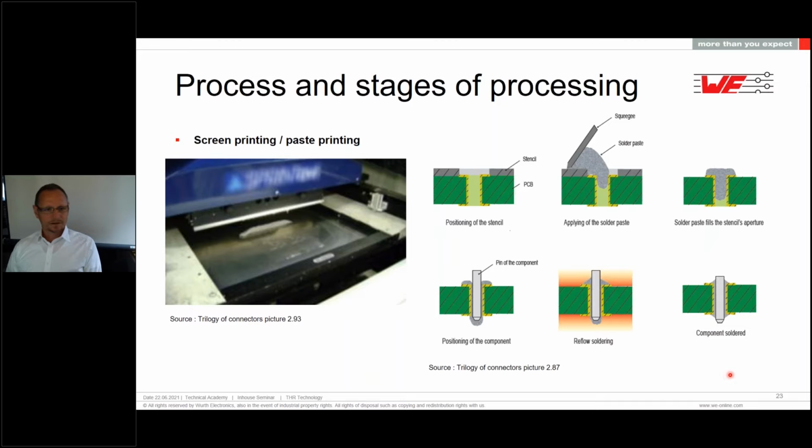Yeah. If you notice some problems, that maybe not enough solder paste is applied into the vias, then you can change some of your settings, like the angle of the squeegee. You have to calculate that the force is always going in a 90-degree angle. So the force would apply here. If you do it more flat, then the force is going more this way. So maybe this helps a little bit.